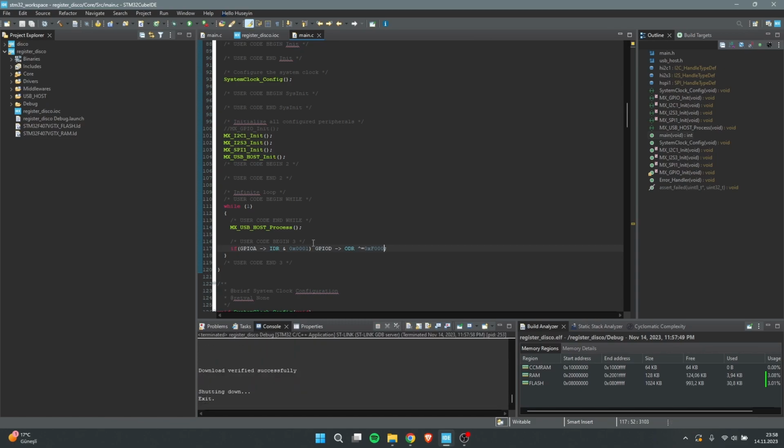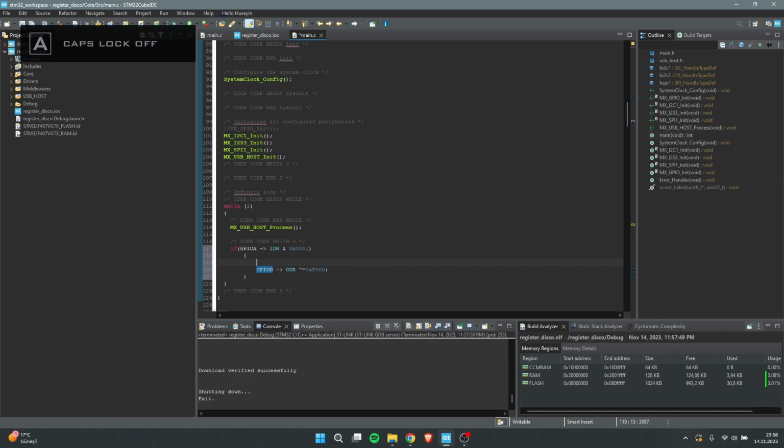For your code to function correctly, you need to specify a debounce time after pressing the button. Otherwise, even with a single press of the button, it may appear as if you have pressed it 2 or 3 times. You can observe the difference by trying it out.